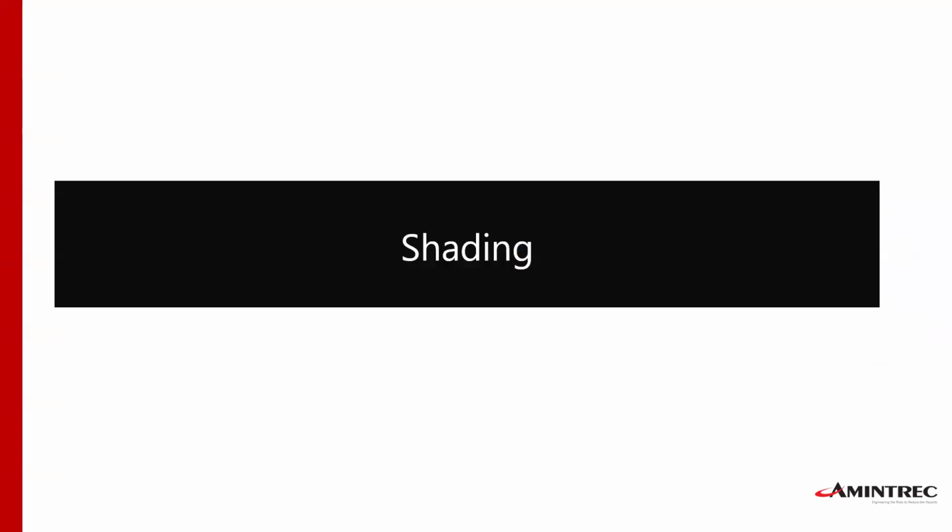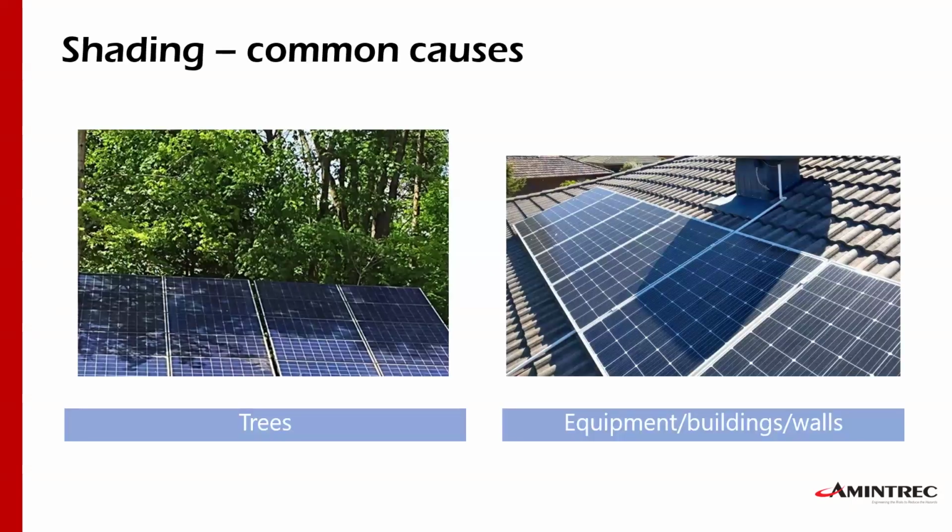Shading is something that we should understand a little bit more clearly, because if the photovoltaic panel is blocked, if it has a shadow effect due to many causes, that will be called shading. The shading will obstruct and will decrease the amount of sunlight received by the panel, and obviously that will be a decrease of the current by that specific panel or by part of that panel as well, and that will create a problem.